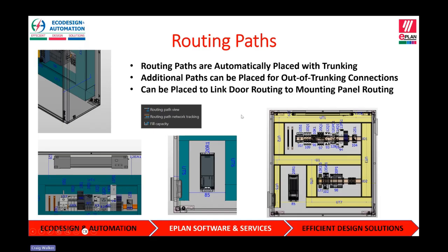And sometimes you're required to add your own. An example of that is this VSD that's been placed here. It obviously needs to be routed. Its connection point designations are going to say route downwards to the nearest routing path downwards. So unless there is a connecting routing path across the bottom of it, it won't find anything to route to. So that's been manually put in. You can put in other features as well. Say if we had 5 VSDs, you'd run a line under the left 3 going left and the right 2 going right and leave a gap, in which case it will find the correct one to route left or right to the closest bit of trunking. So it's quite convenient that way.